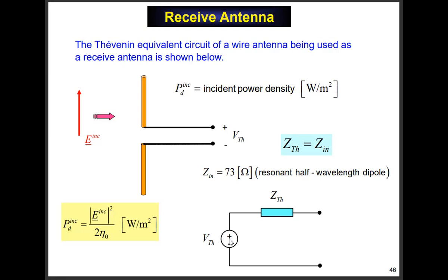So you've got a Thevenin voltage, and I'm in the phasor domain, so a phasor Thevenin voltage. What does that mean physically? Just think about circuits. It means the same thing as open circuit voltage, right? So even though the receive antenna is practically connected to some kind of receiver, in other words, some kind of load here, if you just disconnect everything and leave it open circuited, the open circuit voltage is the Thevenin voltage. That's what it means, right?